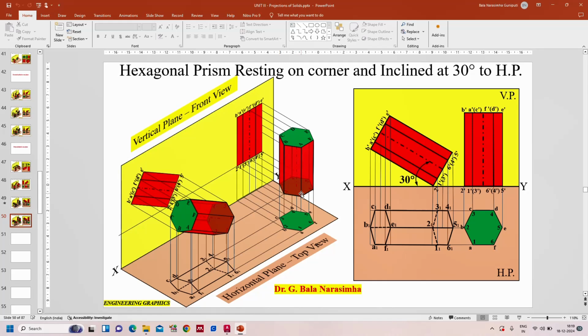The same applies for D4, which is a hidden line, and F6, which is a visible line. When you consider the overlapping priority, first priority goes to the visible line. That's why I am considering F6 as visible; D is invisible, but I draw the visible line here.